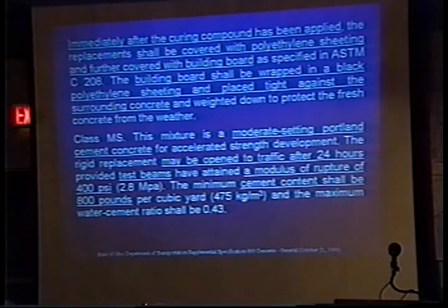So that's a 4-hour mix. It's fairly commonly used, and if you've got joints to replace, small slabs to replace, you might try that. Now, granted, you still have to go through all the rigmarole of jackhammering, saw cutting out the unsound material, jackhammering it out, inserting or putting your dowels in properly.